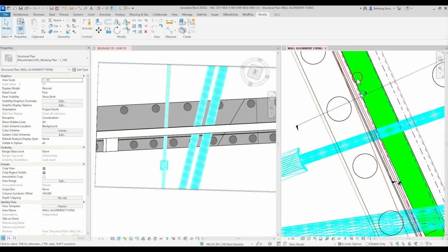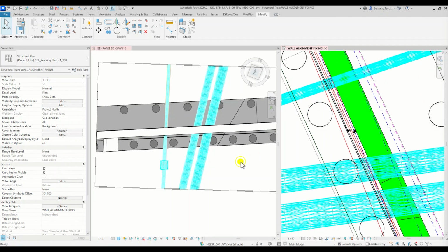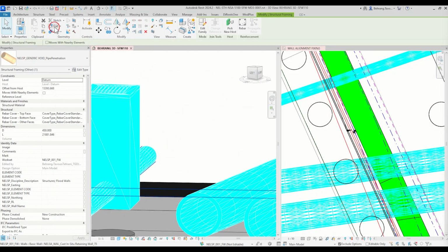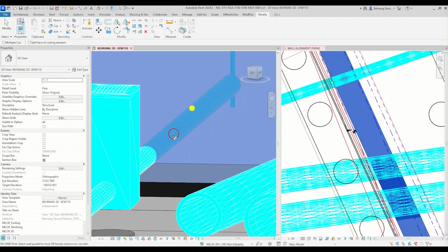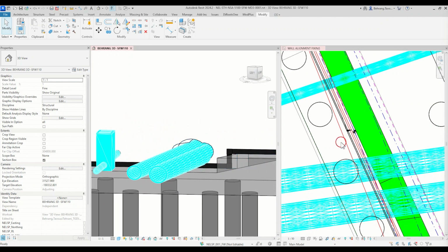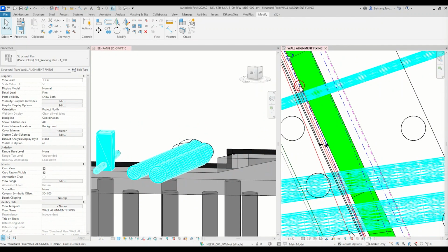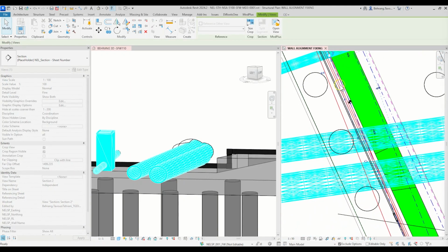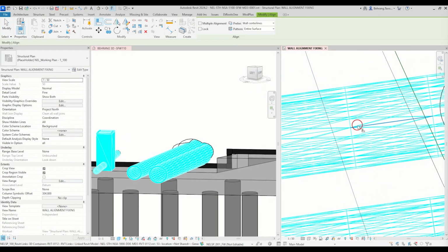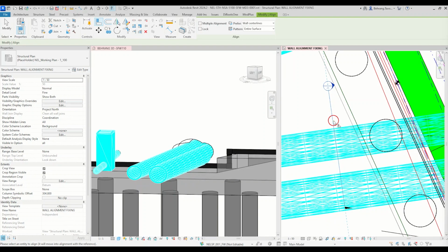So I'm going to close this section too. Now in 3D I just did this one, but we forgot to cut. Selecting the wall, then cutting. So now we cut a hole there. Let's align this section again. Let's pick the section by hitting Tab until we find the section. I will put the section somewhere here. I'm going to zoom in enough, type AL to align, pick this line, then pick our section. So now our section is perpendicular.